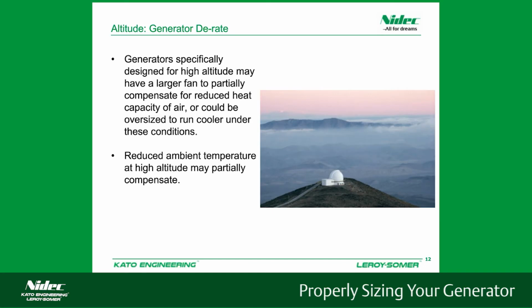One of the things that typically helps when you have a high altitude is there's typically a lower ambient temperature, but we still often have to rate the machine for 40 degrees Celsius, so that can help sometimes, but it doesn't always.